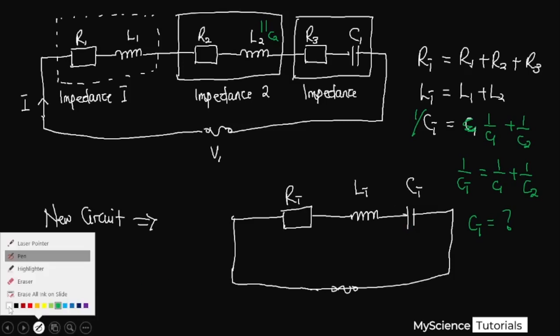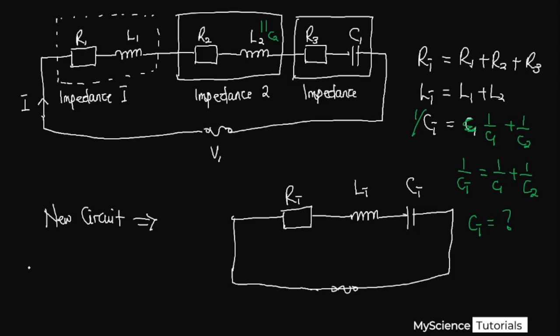So with this basic introduction, and knowing the formula for calculating impedance for a resistor, inductor, capacitor circuit, as we saw in the previous video, our impedance is equal to the root of R squared plus XL minus XC, this quantity squared. This is how we find the impedance in case we have a resistor, inductor, and a capacitor in series.